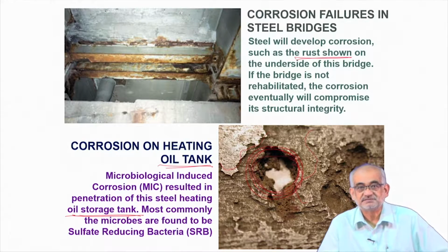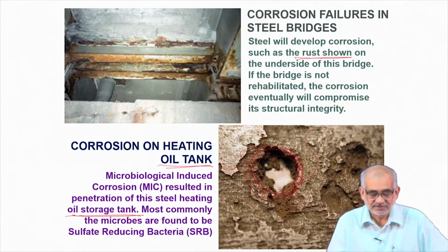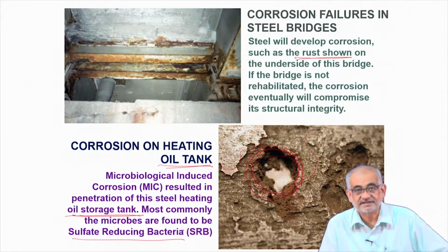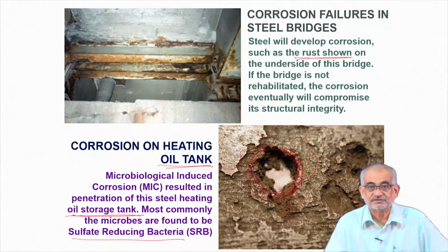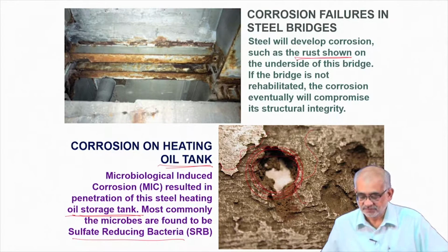So there is no escape from it, because you actually have to have petroleum, and in order to store it you need metallic vessels, and the petroleum will contain a lot of sulfide or sulfur containing fluid, and there are bacteria which are called sulfate reducing bacteria which will feed on such stock, and in the process will cause such corrosion, even form such holes.